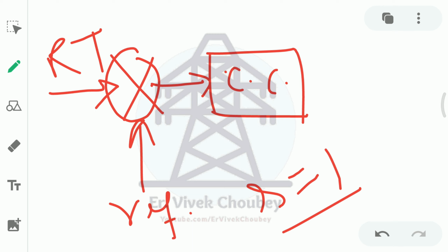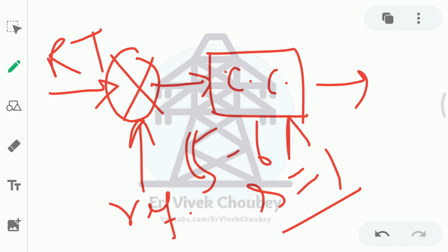So in this case, as there is a difference of 5 degrees Celsius, or even if there is a 1 degree Celsius temperature difference, this circuit will cause the compressor to turn on, and that means the induction motor will draw a huge amount of current. Ideally it is around 5 to 6 amps. This is a huge amount of current because the induction motor is starting from 0 speed. This huge current causes a voltage dip, it is reflected in our monthly electricity bill, and it is also not good for our environment, because coal and other fuels are burned for generating this electricity, and it is just being wasted for what? Just turning on the induction motor.